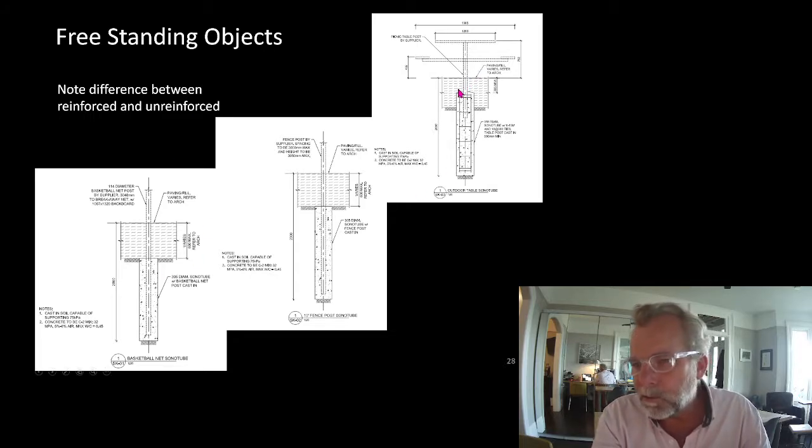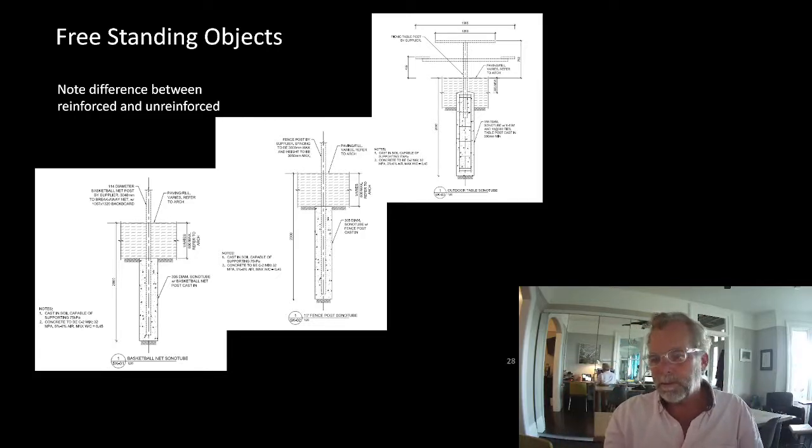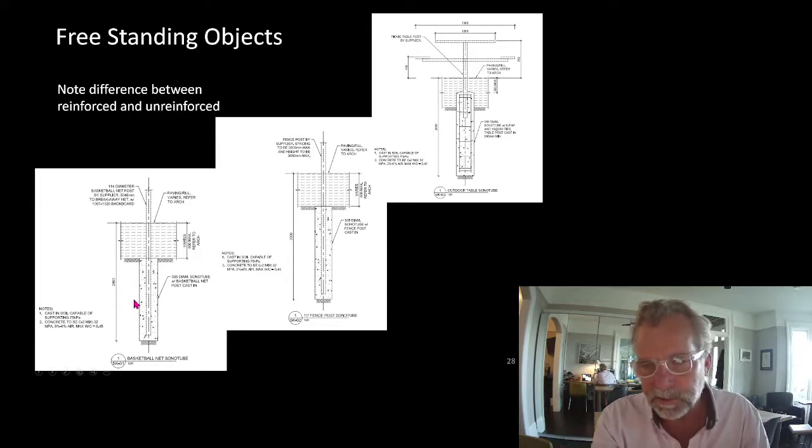Another detail we could have shown is a base plate and 4 anchor bolts. So when you're driving down the 401, you can see you've got giant light standards. They're not embedded into the foundations. There would be a circular array of anchor bolts, and there'd be a big base plate, and that's how the forces get transferred.